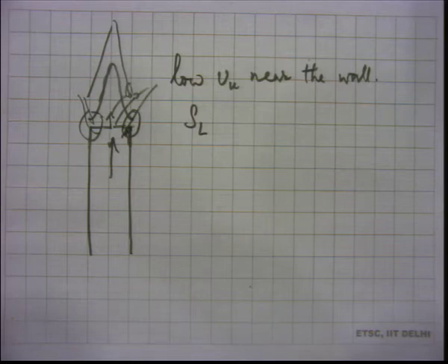This is a complex mechanism, but we have to keep in mind that we are not going to get uniform flow here. Flow velocity is low near the burner rim, but the burning velocity of the mixture is also low. Because it is not adiabatic, it is actually not a property of the mixture at that location. So this gives you some idea of how flames get stabilized.